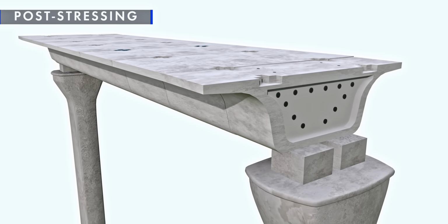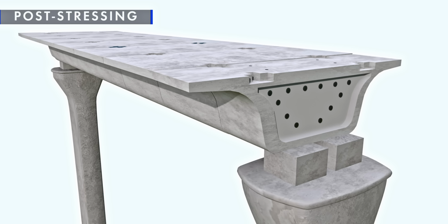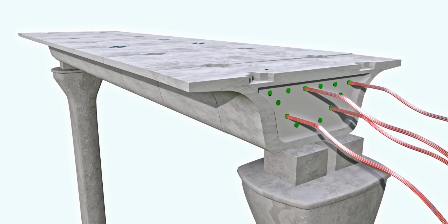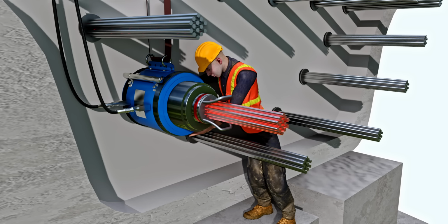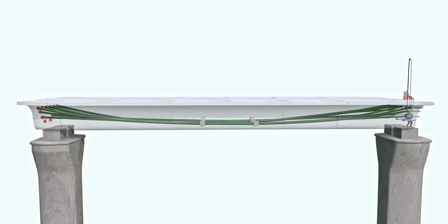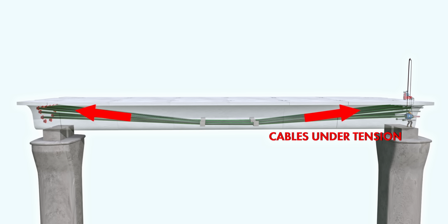There is another method to achieve the same result: post-stressing. Here, we're compressing the concrete after the concrete is solidified. Here, steel tendons are inserted via the channels in the hardened concrete. The workers now stretch the cables using a hydraulic jack, keeping the cables in extreme tension.